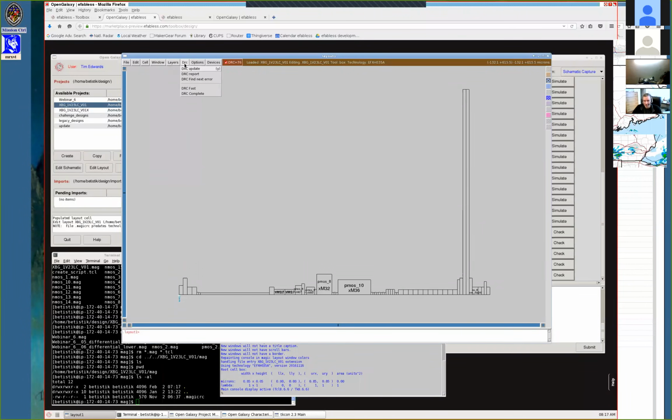There are some options for looking at DRC errors and so forth. Continuing along the top, there's a live view of how many DRC errors you have in your netlist. As soon as it created the first initial netlist, it already ran DRC, and that's the number of errors I have. There's a little information about what cell you're editing and what tool you're using. I'll get into that. There's a view of the position of the cursor in the window.